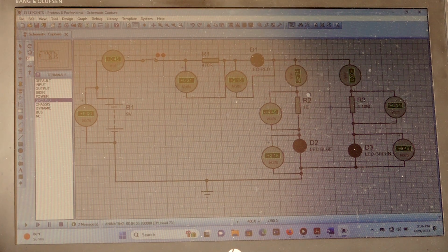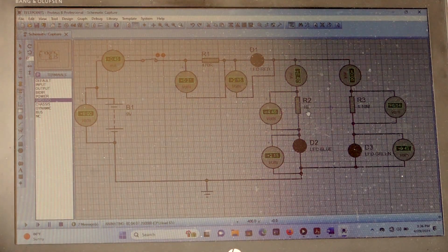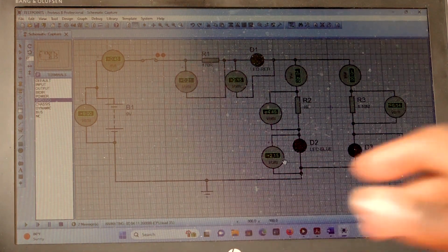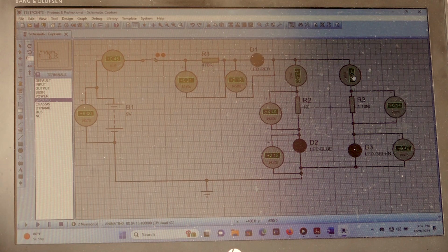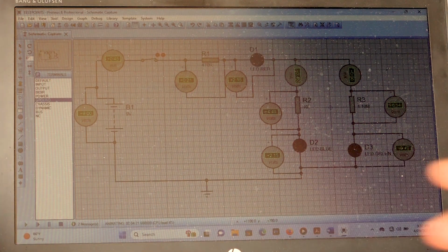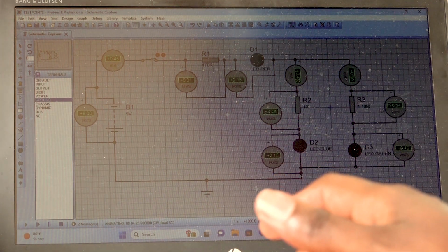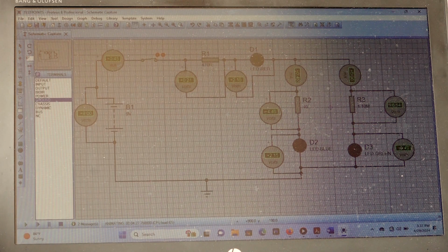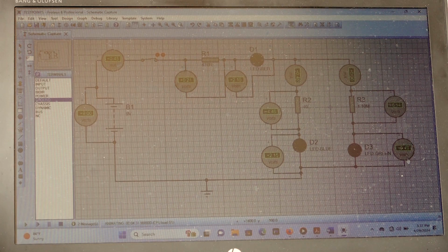Are we together? Yes. Then what is the potential drop across R4? 9 volt. Then the potential drop across the LED? 2.15 volt. What is the current through the network of R3 and D3? It is 0 ampere, right? What is the potential drop across R3? 6.14 volt. What is the potential drop across the D3? 0.49 volt. Check your neighbor.